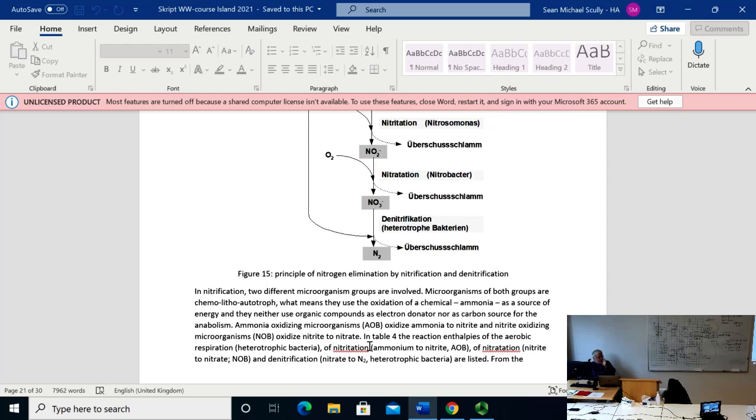Whatever I do there, if I have nitrite it becomes a little bit touchy, because if you don't have a complete nitrification, then with the denitrifying processes you might run into N2O production. That's what I learned. This was what a guy from Vienna University once commented at a conference. This was a small conference in Boltenhagen, initiated by an electric equipment supplier.